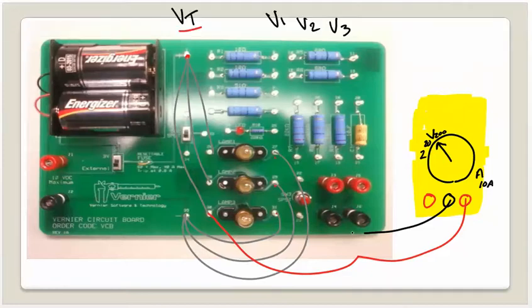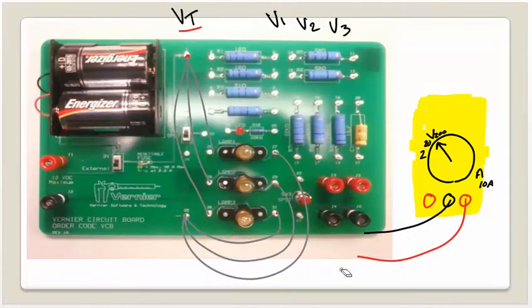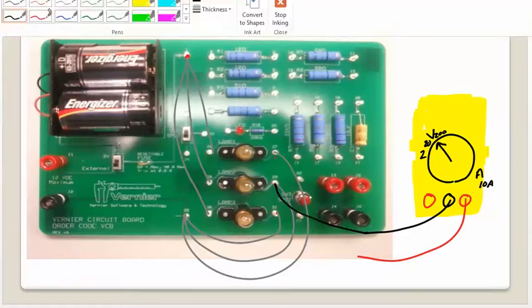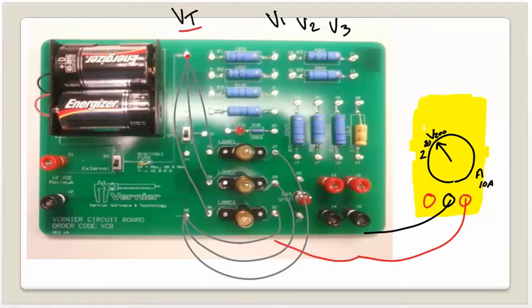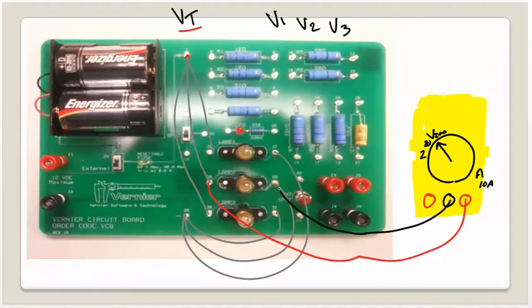Measure there. Remember that we're not going to be disconnecting any of the wires when we do voltage. Or, if I want to do the second one, I would go there with it. Or, as I said earlier, I would take the red one up here, and I would take the black one up here, and that's how we'd find those individual voltages.